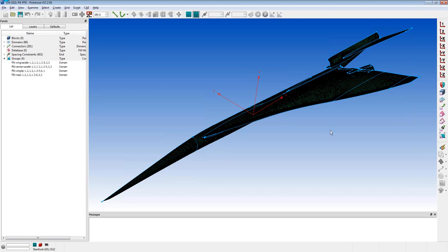Okay, and groups are great because they provide a mechanism for doing selection. And so you can create a group of domains. For example, when we're creating these boxes in 3D, we would create a group of domains. We would create a box around these domains and scale it, give it the appropriate dimensions, and then we could export that as an FFD box.